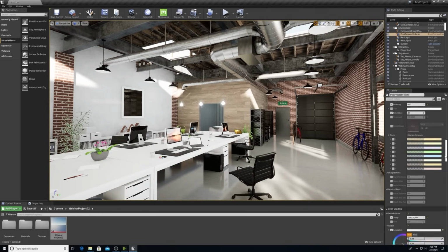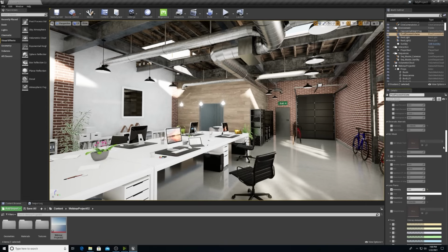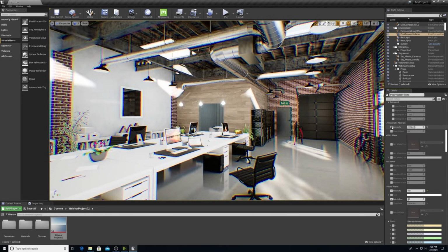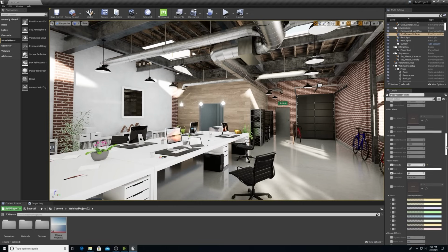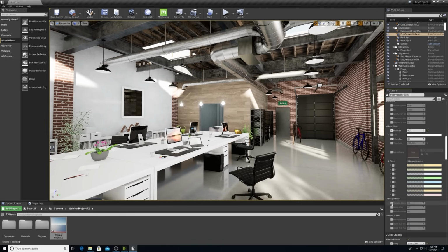There's also options to make it a little bit more realistic. You can add some chromatic aberration in. You can add depth of field, play with your lens flare. Maybe I'll add in a little bit of vignette on the sides of the viewport. And there are a lot of options here, and I won't go over them all, but I do want to bring it up so that you know that you can create a style that you are happy with.